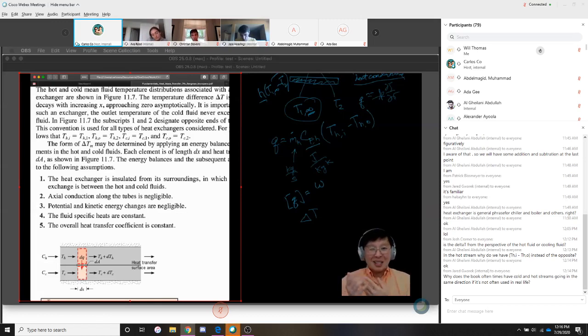So for me, at this point, if you choose to forget everything I taught you in this class for heat exchangers, the only thing I really want you to remember is counterflow. Don't ever go co-current, okay? You go co-current, the risk of getting fired is quite high because everyone knows you have no clue what you're doing. That's the minimum you need to remember. And we'll go through more details of how to do the heat exchanger calculation. So I start with the most important thing you need to remember.